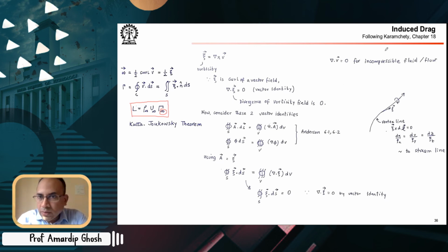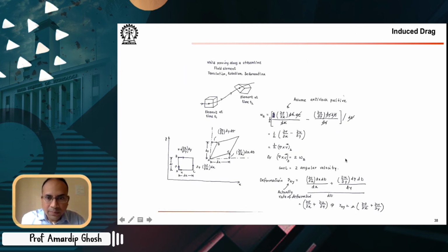So, okay, now with these two ideas, that the vortex filament strength is conserved across cross sections, and secondly, that the lift is related to rho infinity u infinity times circulation, you can now see that circulation, remember, is nothing but the strength of the vortex filament. So there is something to do with lift, circulation, and the vortex filament induced velocity field in the neighborhood of the wing. So we will now get into that part of the discussion.